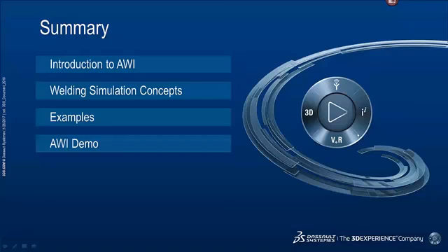The details obviously are proprietary, but it does what it is supposed to do, which is give you the behavior equivalent to model change. The basic feature of any material activation method should be that you can't have a jump in stress when the material goes from inactive to active, because when the material is inactive, it is going along for the ride, but it does have a certain amount of elastic strains in it, and so a certain magnitude of stress in it when it is active.